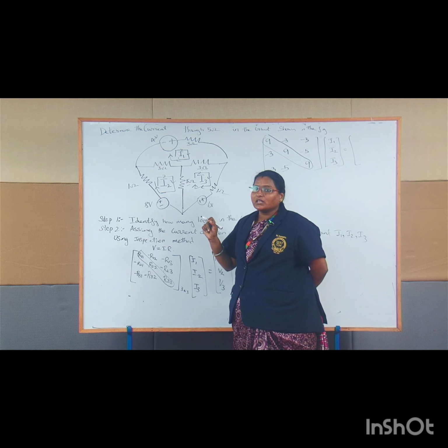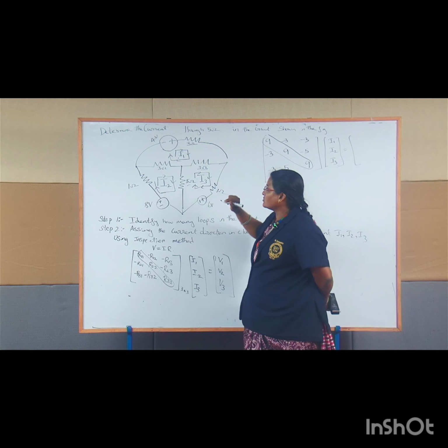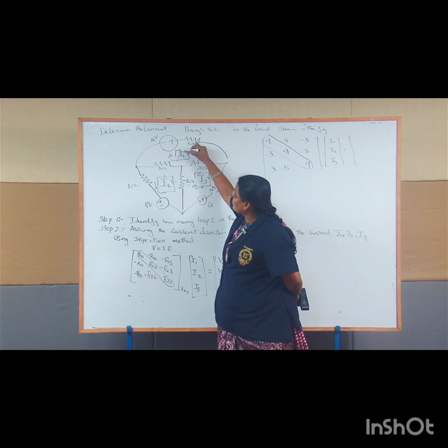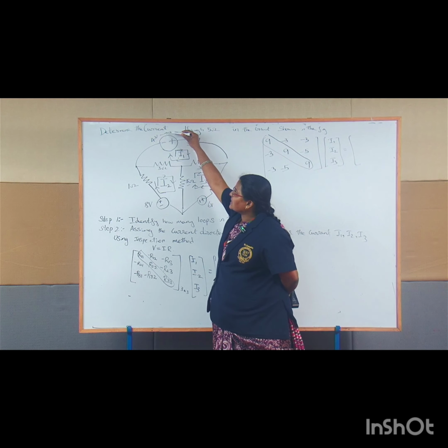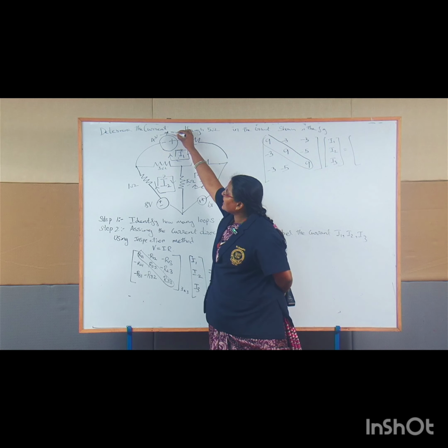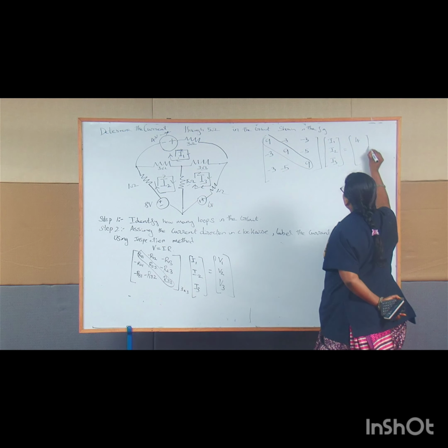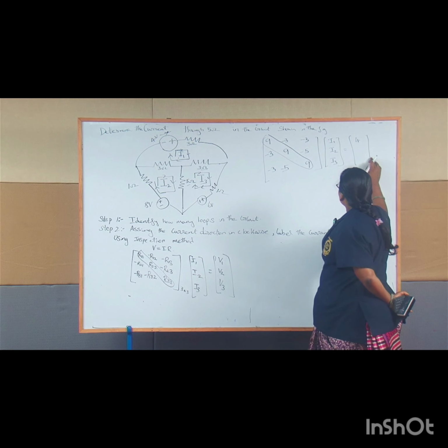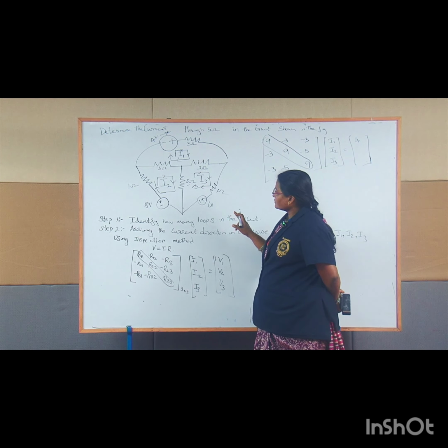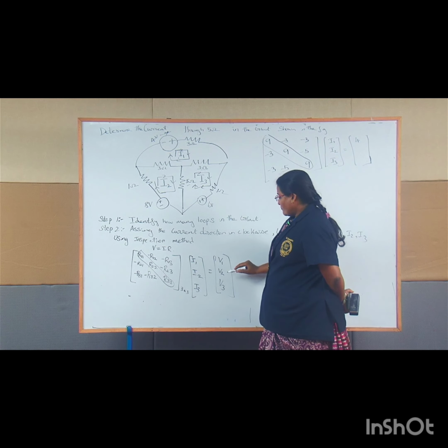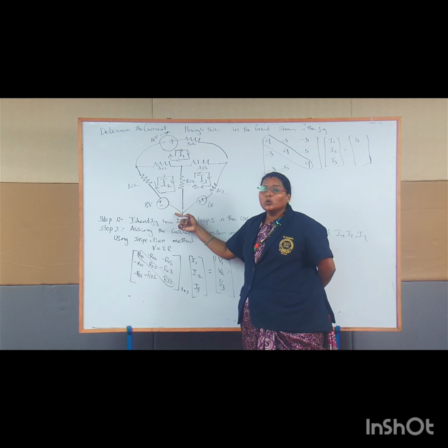Once you check with the voltage, you have to check with the assigned direction also. So here the direction goes like this, right? This is my assigned direction, clockwise, minus plus. So the arrow head ends at plus. So you have to write positive 4 volt, right? Then V2. V2 means the source voltage present at loop 2.